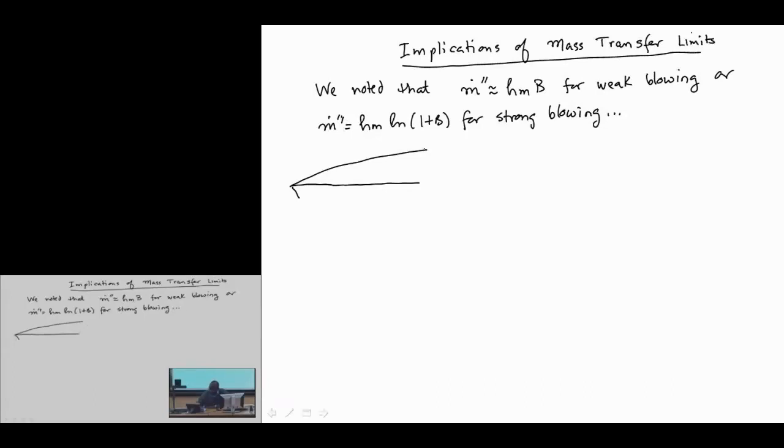So this is our Y boundary layer, where there's some Y surface here, and we can even say Y is equal to 0 outside here. Okay, so diffusion allows the transport of Y from the surface into the free stream, and there's growth of this boundary layer.